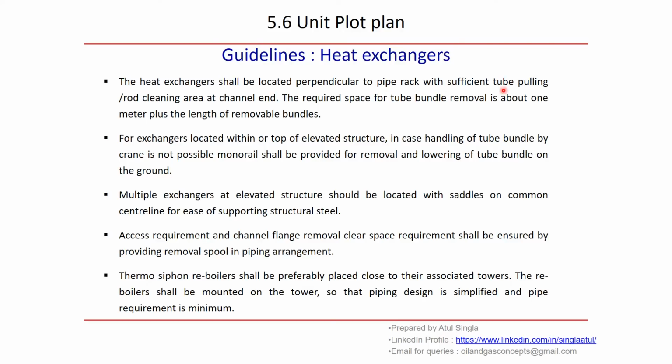If you see any exchanger, we have to have a bundle removal area, so we have to allocate space for that. The required space for bundle removal is about 1 meter plus the length of the removal bundle. Whatever is the length of the bundle, we add 1 meter to that, and that much space we keep for maintenance or bundle removal.